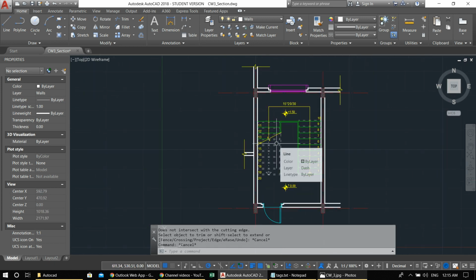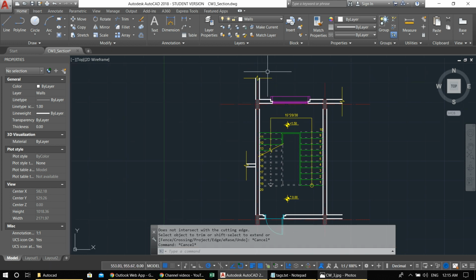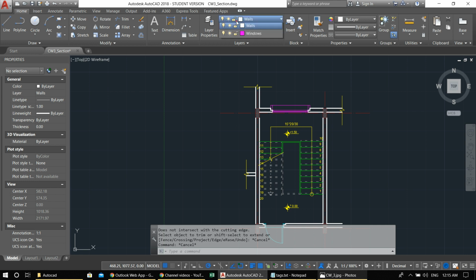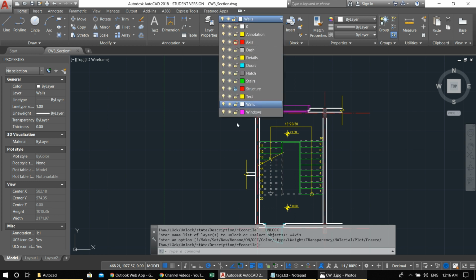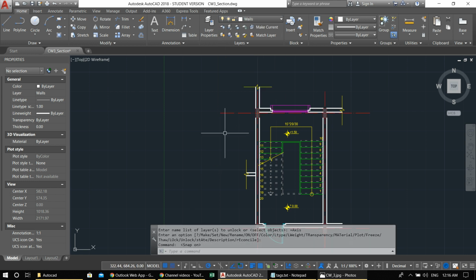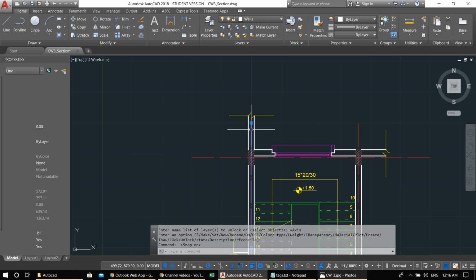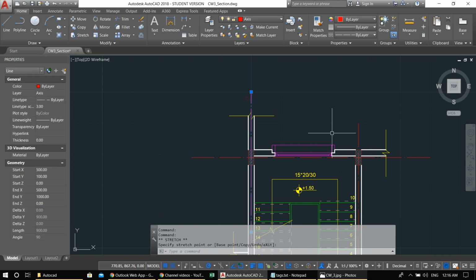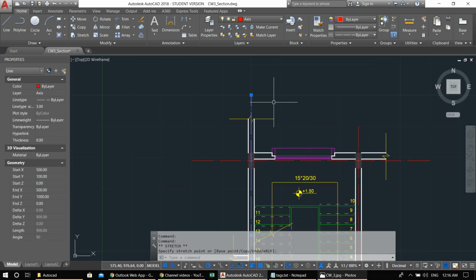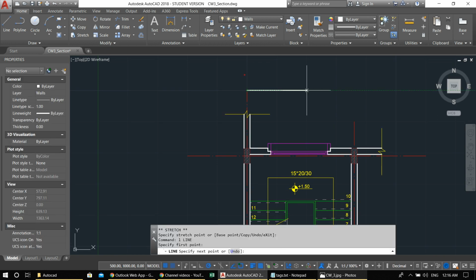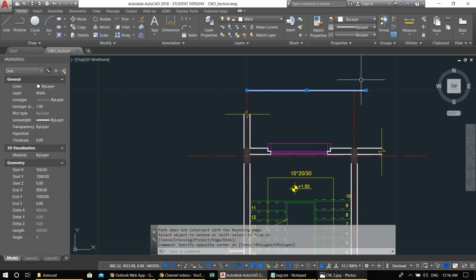Now, what else? We have the section lines and we have the bubbles for the axis. So let's first unlock our layer axis. Let's again snap to grid, because this is a little bit too short. So I'll bring it here. I'm drawing a line, extending this layer, EX enter.